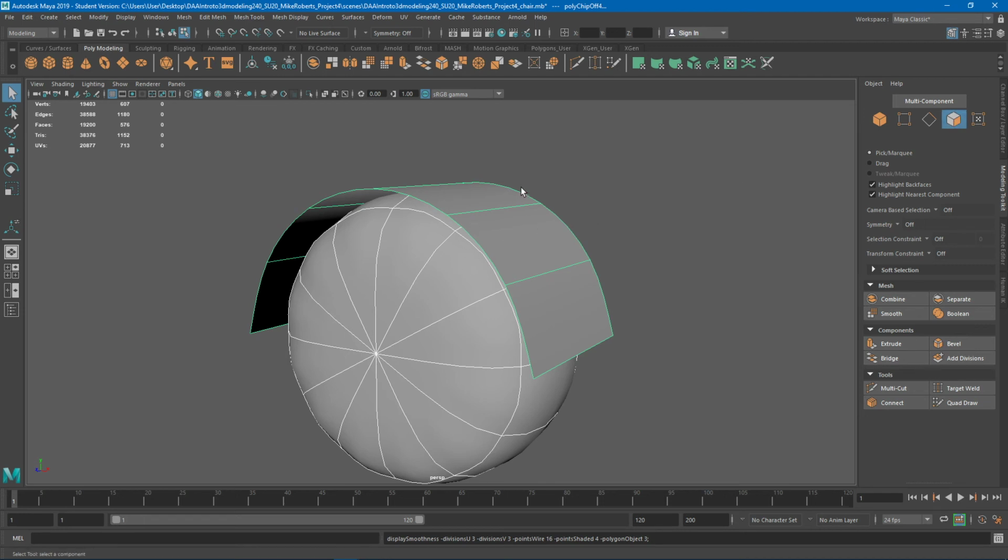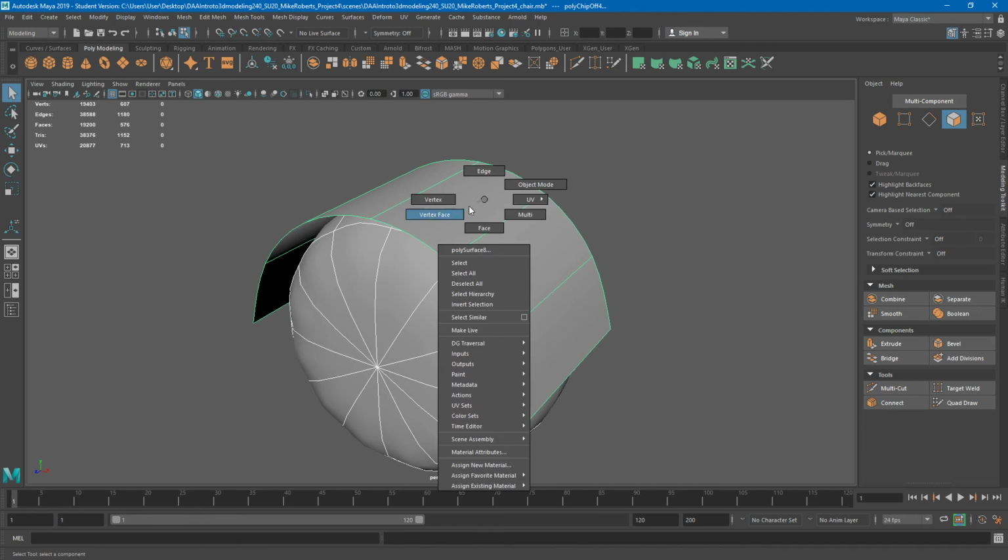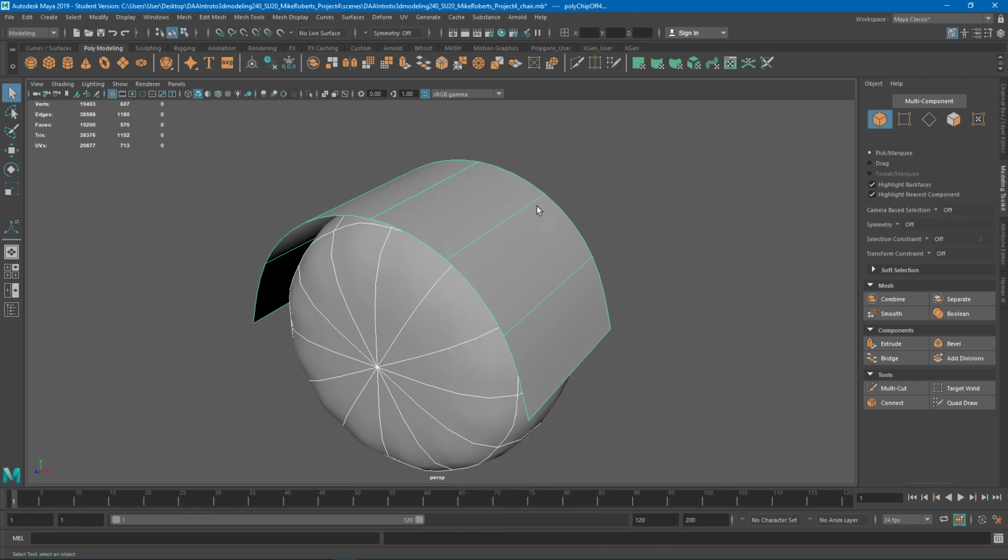So even though it looks like it's on object mode, sometimes Maya is still confused. Remember, these are your selection types right there. There are quick keys for them, F8, F9, F10, F11. But a lot of modelers, including myself in Maya, prefer the marking menu for this stuff, right? Hold down the right mouse button, and there they are. And you just go back to object mode there.